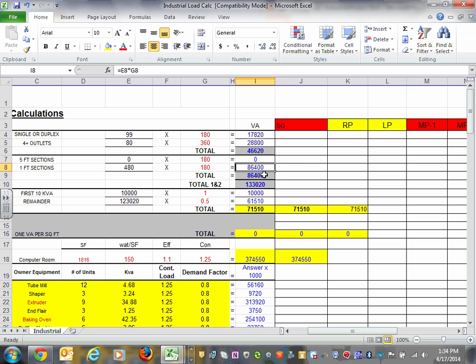So then the rest is in the Excel sheet. That's why I didn't put them in a PowerPoint presentation, because Excel shows you the math behind it, it's not rocket science. So you total them, basically the multi-outlet assembly with the receptacles, quads and duplex. Cool? So we total them right in here, the sum of the two. That will be the connected, so-called, if you use SKM, that will be your connected volt amp in SKM, just the connected.